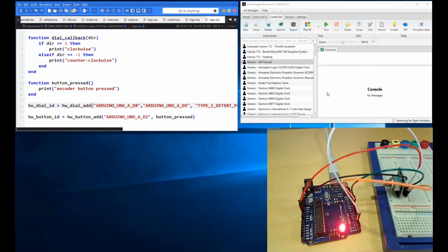Oh no, before we actually run, I just want to explain very quickly how this is connected up. It is particular to this encoder, so not all encoders will have the same sequence or connections, but they will have a similar set of connections, so it's important to talk about what we've got connected here. We've got a power and a ground this time, so you can see I've still got the ground wire in there, my black one here, and this time the black one is coming over directly and connecting to the ground terminal of the encoder.